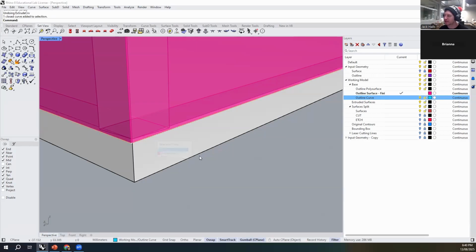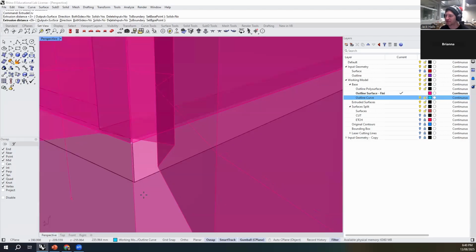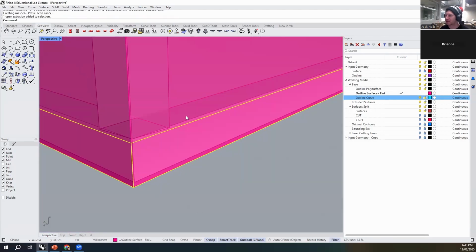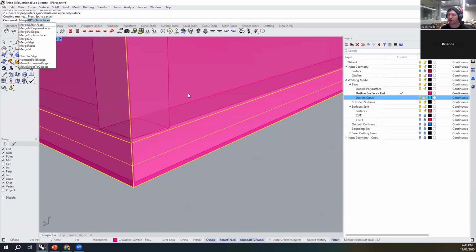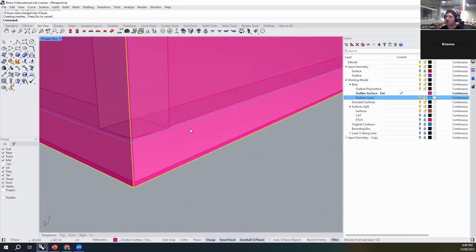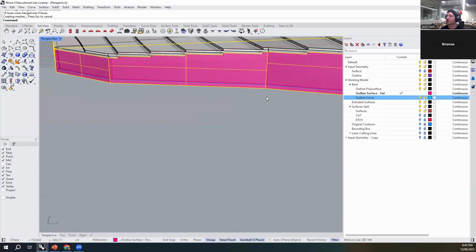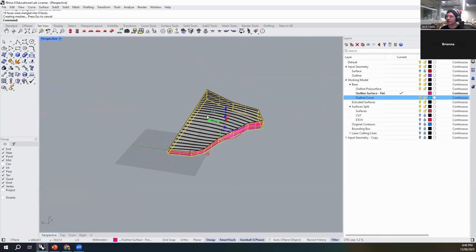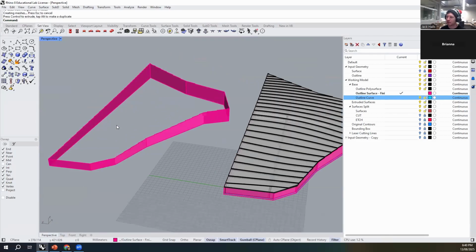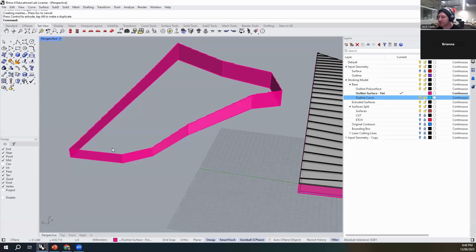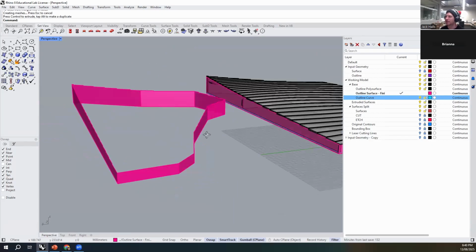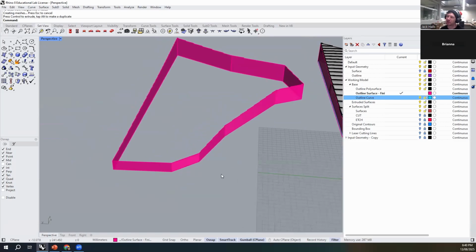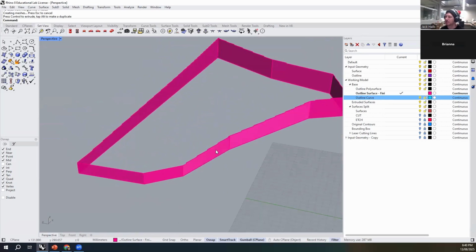So take that curve, and I'm going to do an extrude. We're going to make sure we don't have solid on. Just pull that down, that'll make it easier. And join those together. I'm then going to use merge all coplanar faces. And you can see that it then merges those into coplanar faces. So assuming that this pink strip on the outside, if I just drag it out as a copy, we're going to use as a guide for laser cutting our edge finishing strip out of black optics card in my case, which is 300 GSM.